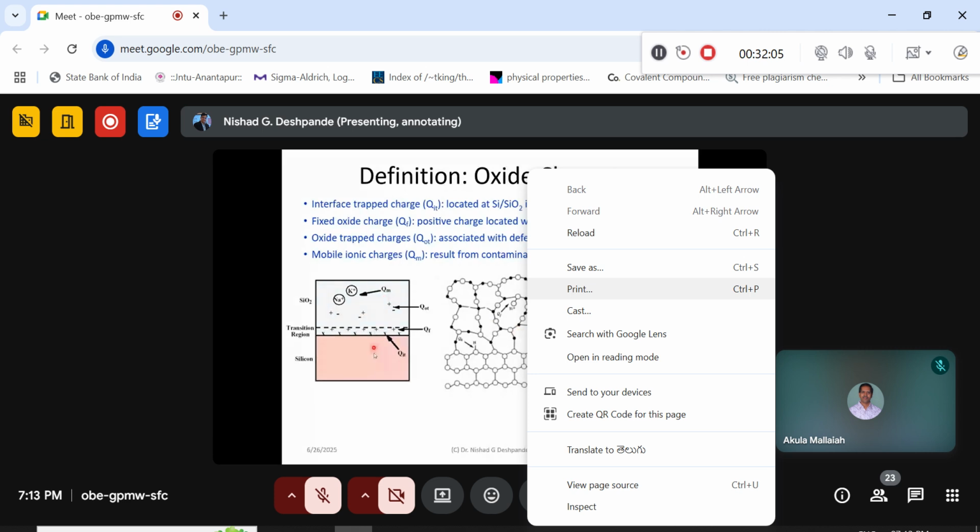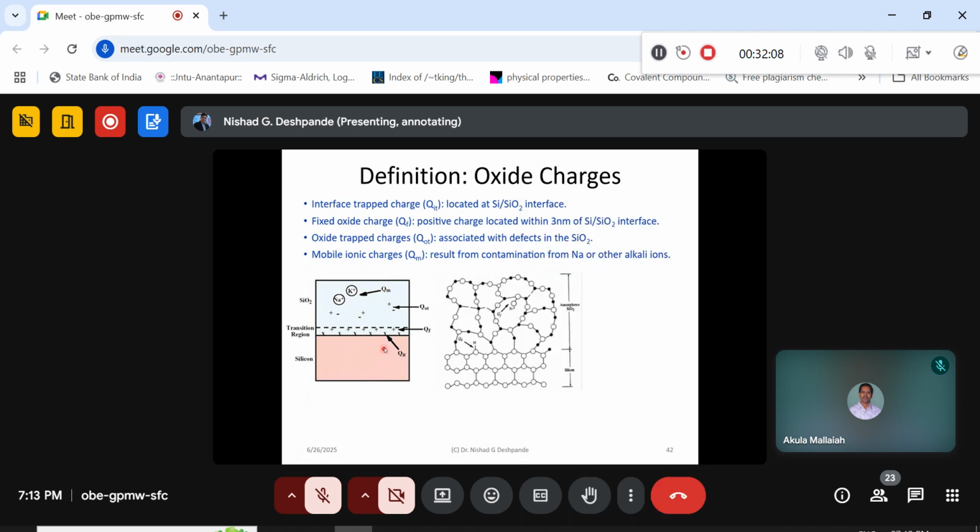I was talking about the epitaxy, right? As the silicon dioxide grows, if it follows the same crystallinity, it will have a very good epitaxial growth of silicon dioxide on the silicon surface. But let's say it does not happen, and this is what is happening here. Again, a very important part comes into the picture, that is the defects. We can see clearly that there are defects being formed. Because of these defects, you have stacking faults, and these stacking faults will play a very significant role in your output characteristics.